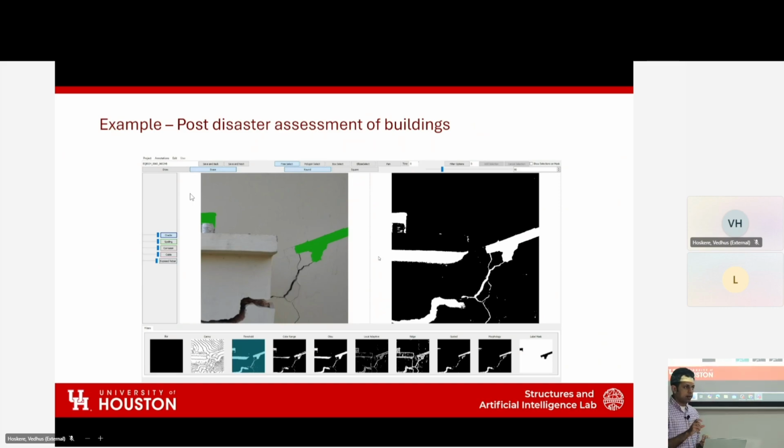If I had to do that manually, then it's very hard to stay in between the lines precisely, and it can be really time consuming. On the other hand, you can use the fact that there's a big gradient change here, and so many image processing filters will allow you to highlight that difference. So here what I've done is I've implemented several different image processing filters, which are very commonly available in a package called OpenCV, plus some additional methods that were developed specifically for detecting cracks.